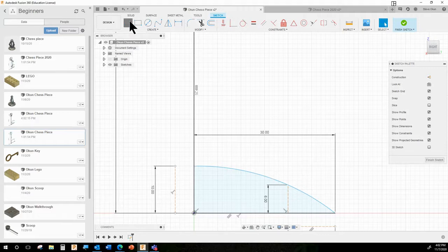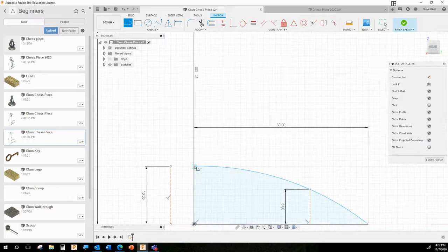So once again, I'm going to make construction lines because that's a big part of what this lesson is about. I'm going to start at where the base connects with the center axis. And I'm going to click and draw a straight line out, making sure I'm going straight and not at an angle, 0 degrees in this case. I'm going to type in 12 and click OK.